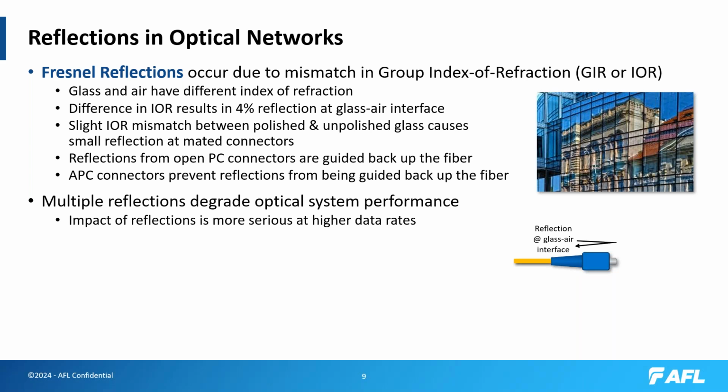As people go to advanced modulation schemes, such as QAM or PAM, that also reduces the eye, and those modulation schemes will be more sensitive to a poor signal to noise ratio.